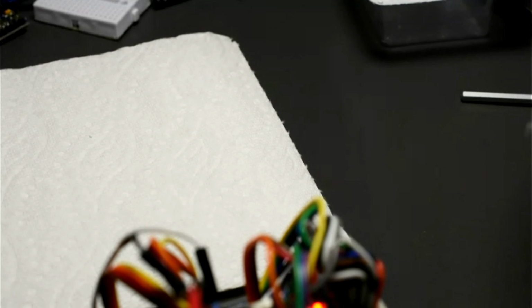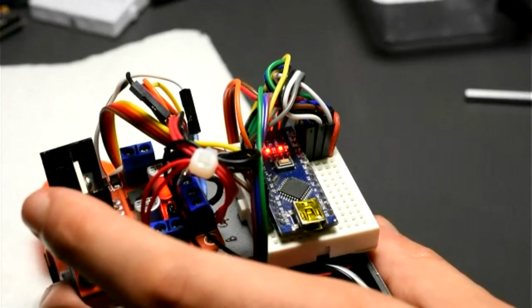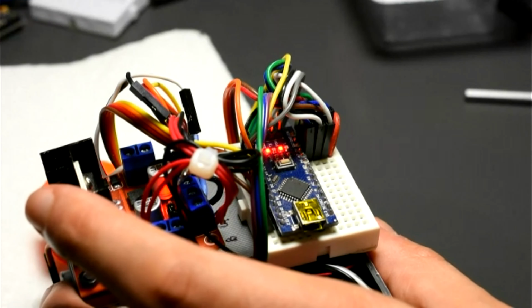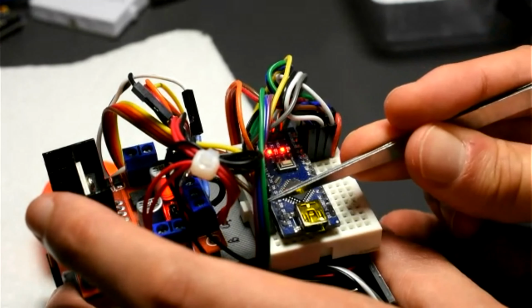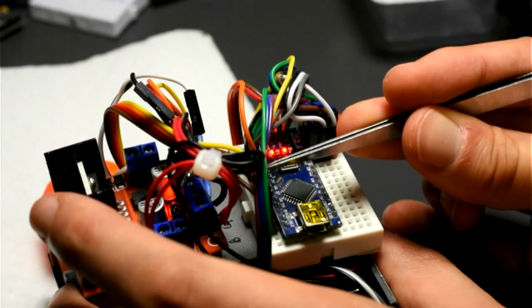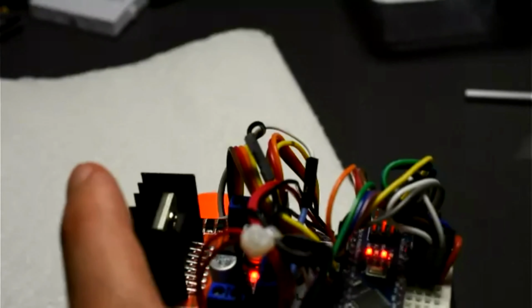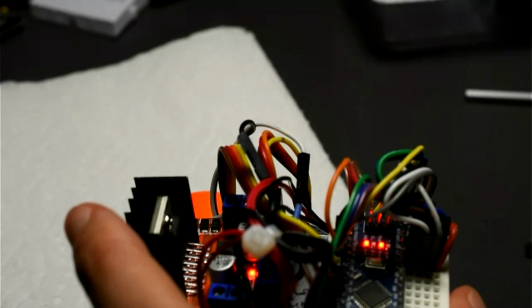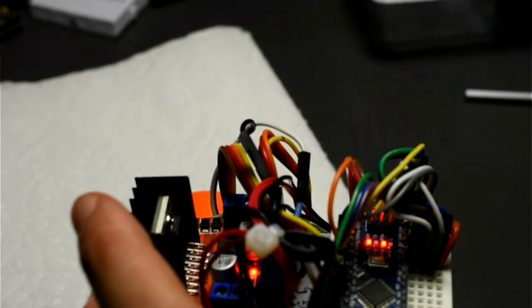So what I'm doing right now is I've checked my pins. I set up in my code 6, 9, 10, 11: 6, 9 for one motor, 10, 11 for the other motor. And oh my god, I figured it out. What was the mistake? Okay, so basically, and this is total coincidence, remember the keyword I said is 6, 9 for one motor, 10, 11 for the other motor.